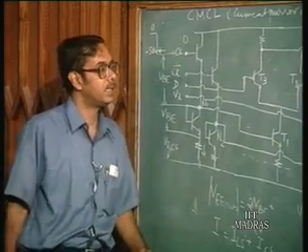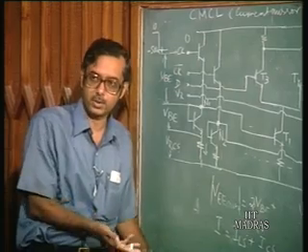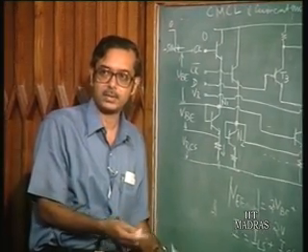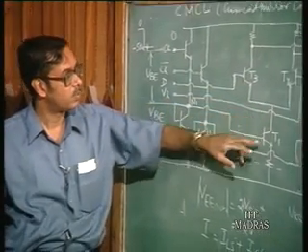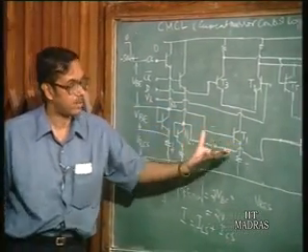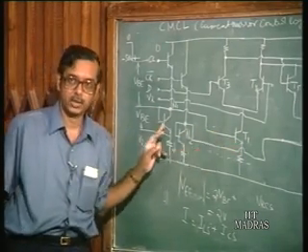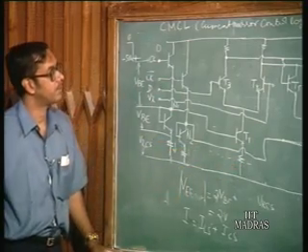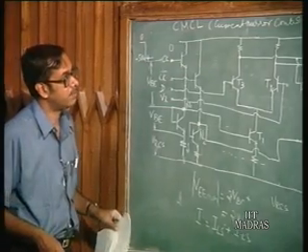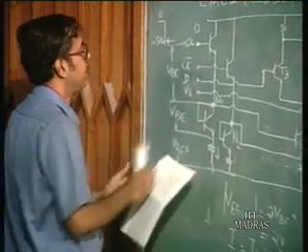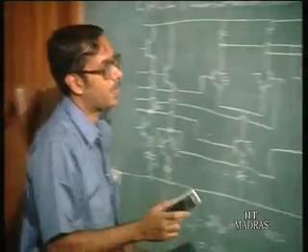All right. So, in fact, this is a D flip flop. Using the same concept here, one can actually realize other logic circuits also, just like a 2-level stack. You can realize other logic circuits where the lower level is actually controlled not by an emitter coupled structure, but by a current mirror arrangement, as given here. I will just quickly modify this. It is easy for me to do on the blackboard.